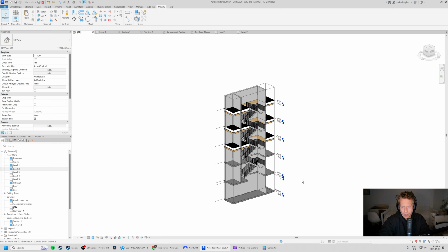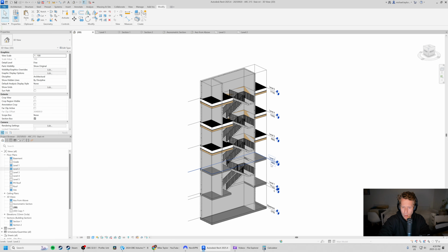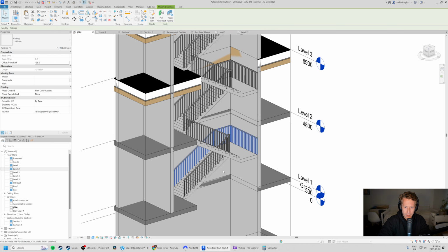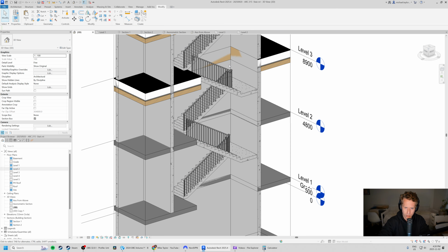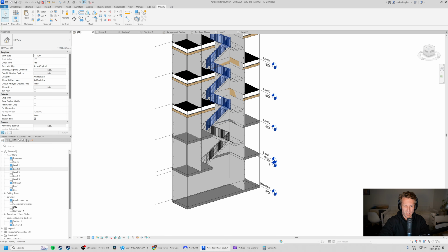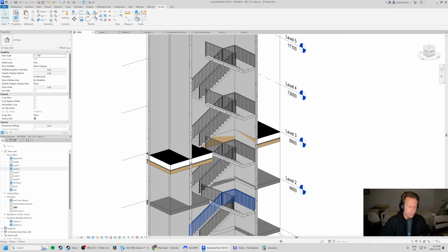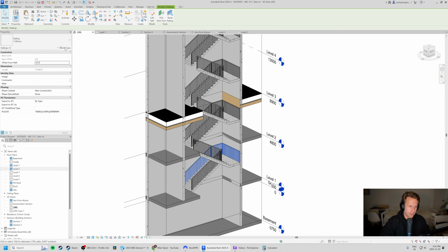So that's roughly the stairs. That's a relatively straightforward way of doing stairs. Stairs are one of the most complicated things you can learn in Revit. So I appreciate the pain of getting through it. I should mention that in this case, we really don't need the guard on the side that's facing the concrete wall. So you're welcome to delete the edges here. We do need to have a railing though, right? So I'm just realizing we do need to have a railing. So we'll have to find a family that we can use. I don't think there's one baked into this.